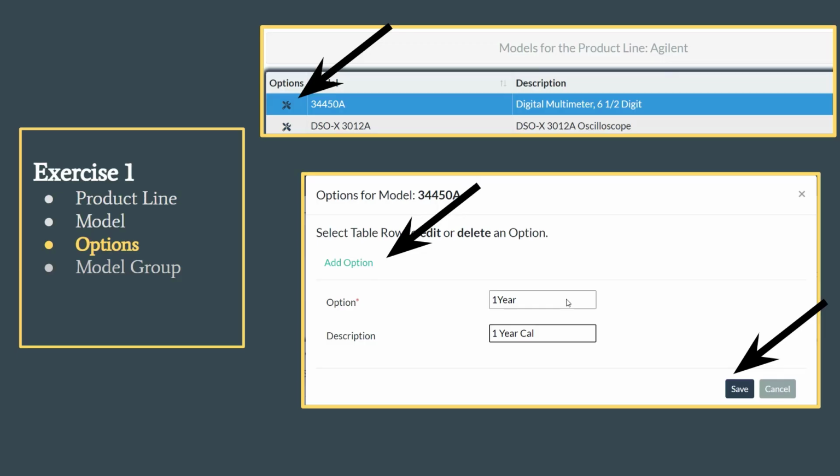And you can go down the list of options that affect the calibration data points, because we're going to select calibration data points on complex instruments based on those options. So Scott out there is calibrating multifunction calibrators. And when he's got a 5500 in for cal, he may have an S3 SC option, or he may have an S6 option. Those would be options that he would put inside of here.